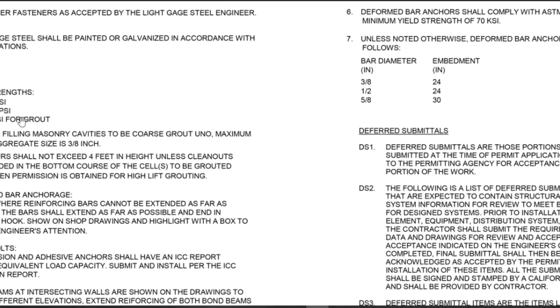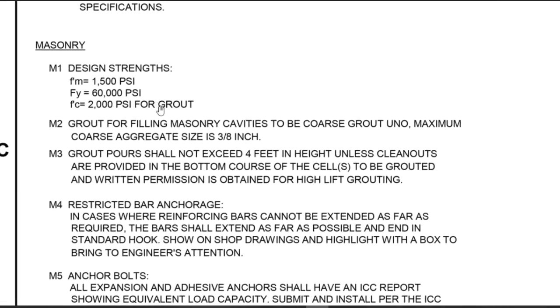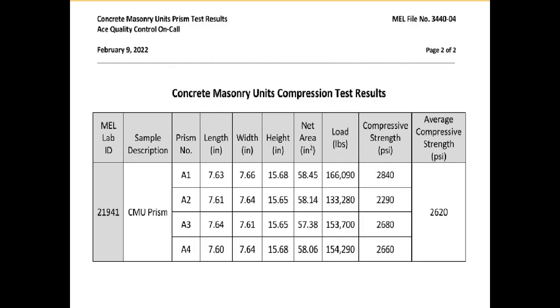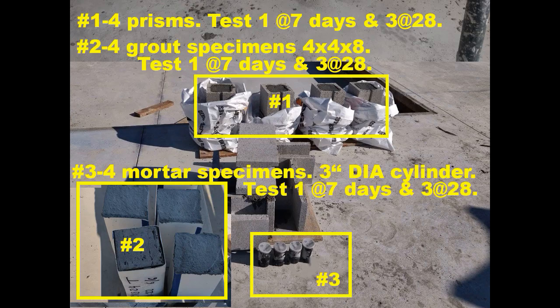Product system description. Design specified compressive strength of masonry. The specified compressive strength of masonry, f'm, is indicated in structural general notes for each building to be constructed with masonry. Verify specified compressive strength of masonry using the prism test method by certified special inspector and laboratory break results.